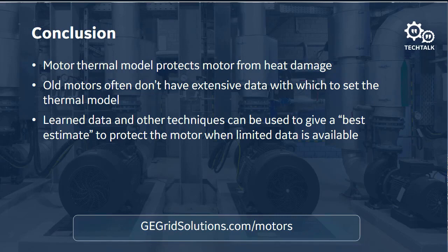So I would allow minimal overload of that particular motor. I would make the assumption that I do not have any capability to overload that motor, that the service factor is 1.0.